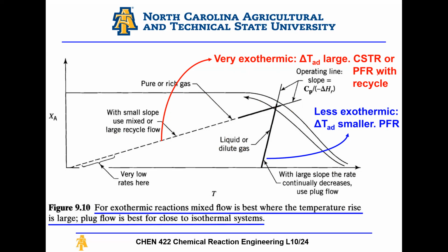So for a PFR with recycle, as we said, as the recycle approaches infinity, the performance approaches a CSTR because I have a lot more mixing. A CSTR inherently has significantly more mixing than a PFR, and better mixing implies better heat transfer, which implies better temperature control. It means you can move your temperature along the locus of maximum reaction rates, as we said previously, and have better control on how to achieve this.